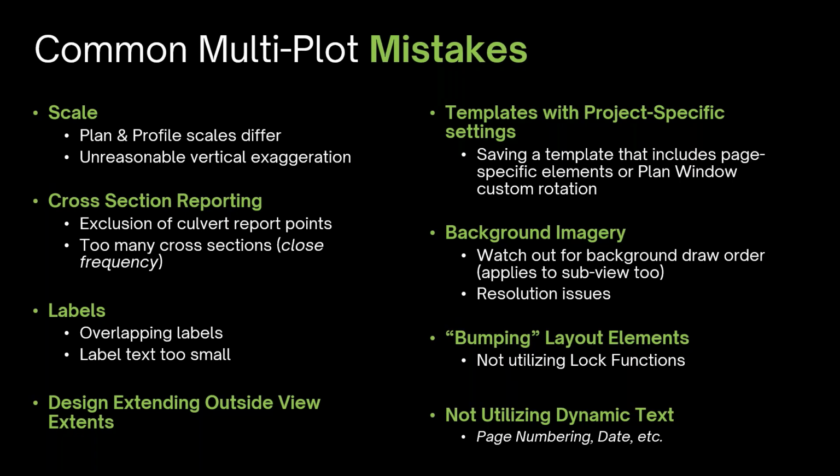In terms of the section layouts, we often hear, why is my culvert not showing on my page? And that is because they have excluded the culvert report points. So the section window is controlled by report points, and you do need to select to include them. The other thing we often see when it comes to cross sections is that there are too many of them and the frequency is really close. So Matt's going to demonstrate today how you can control what's being included within your section window in multi-plot.